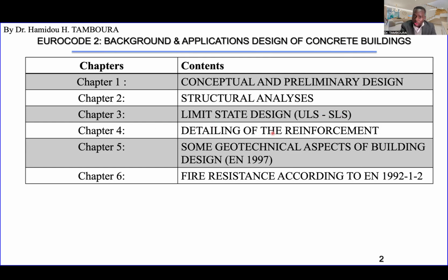And number 4, maybe the most important one, will be dealing with detailing of the reinforcement, because designing concrete structure is mainly about the reinforcement. The reinforcement bars, the number of bars, the diameters, the layout, the position of each bar of reinforcement.